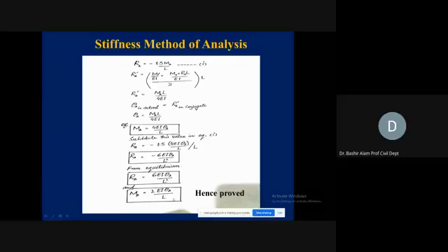Now, if somebody is asking me that let's say some theta is given at an end of a member, you tell me how much will be the actions generated. I'll say at the same end, which is the near end, moment will be generated in the same direction as the theta. And it will have a magnitude of 4EI theta A divided by L, let's say A was the end.